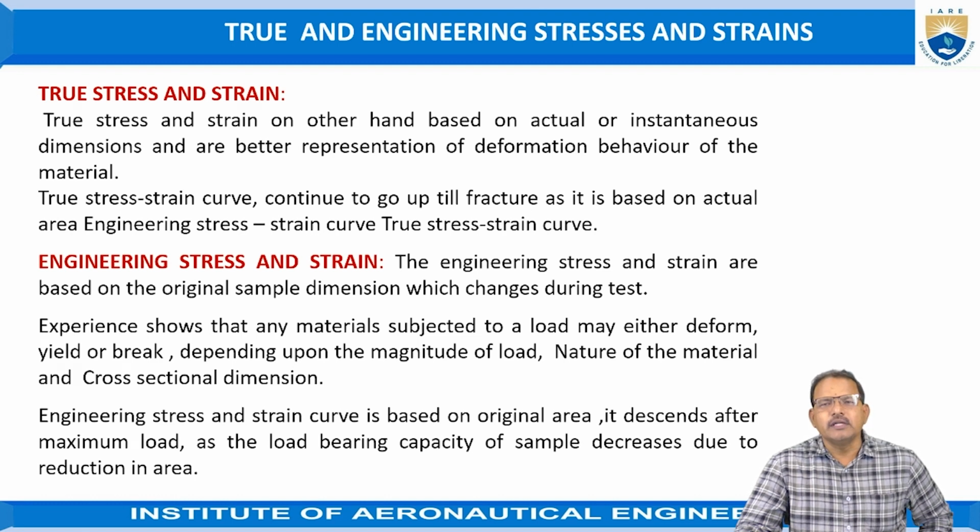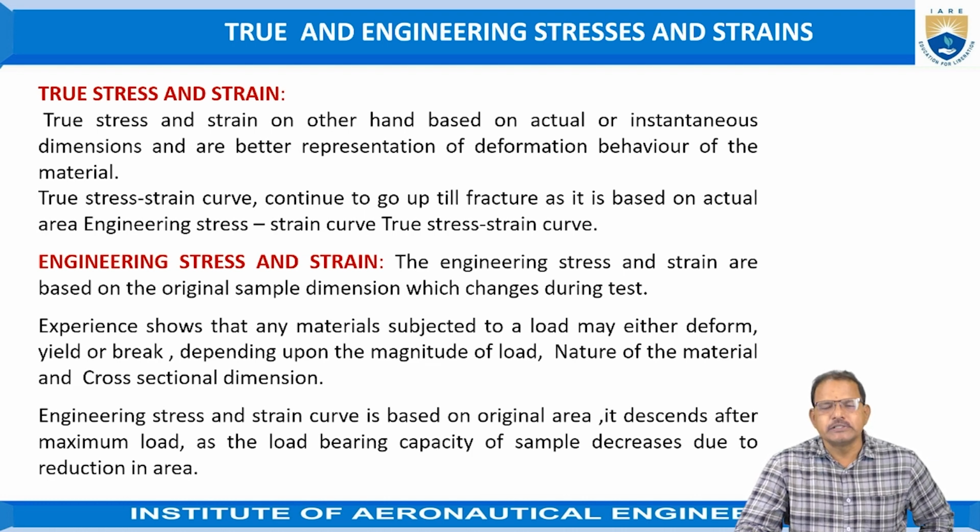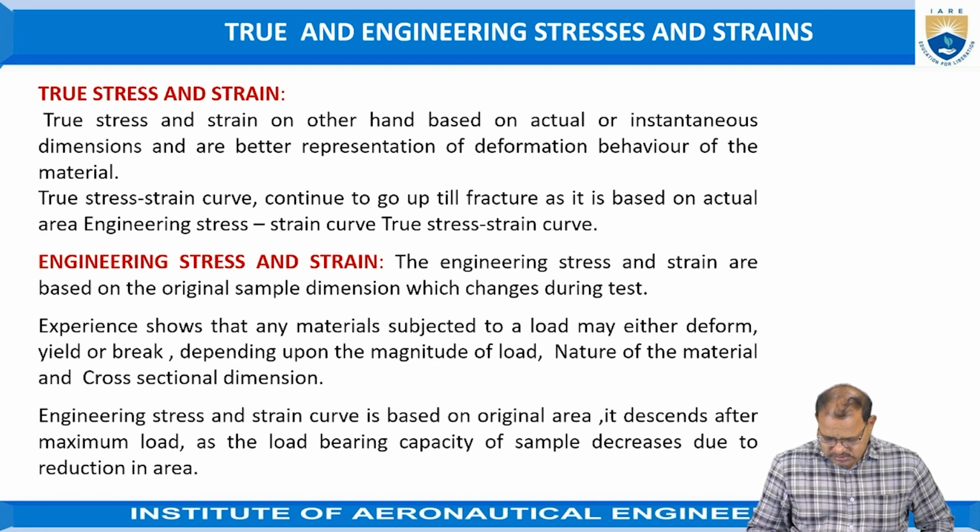But in the case of engineering stress and strain, the engineering stress is the force applied over the original cross section of the specimen. Practically, we draw only engineering stress-strain curves for the specimens in order to predict the mechanical properties.